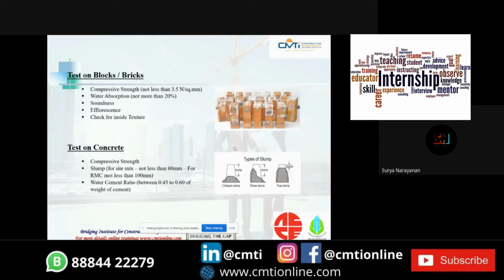So, tests on blocks. Testing on blocks is done by compressive strength, which should not be less than 3.5 Newton per mm square, and a water absorption test, which should not be more than 20%. Then the soundness test and efflorescence test, as you can see in this image, which gives white patches on the bricks when immersed in water for 24 hours. We should also check the inside texture, whether any cracks or scratches are found.